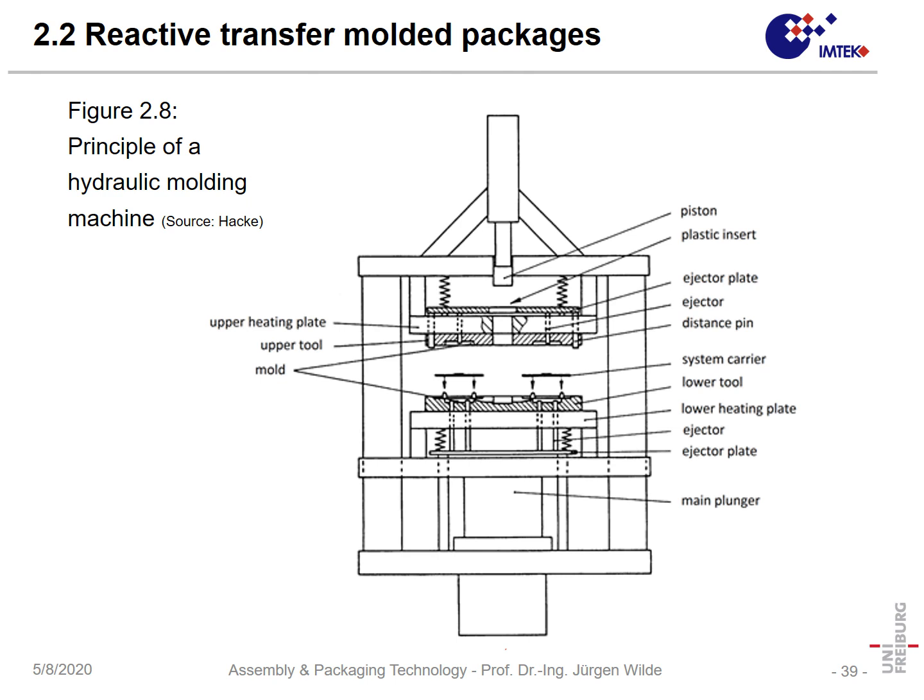The piston will shoot the molding compound into the runners. The material will be liquefied, and in that way it is filling the cavities, and after the cavities are filled, this material hardens within a minute or so.